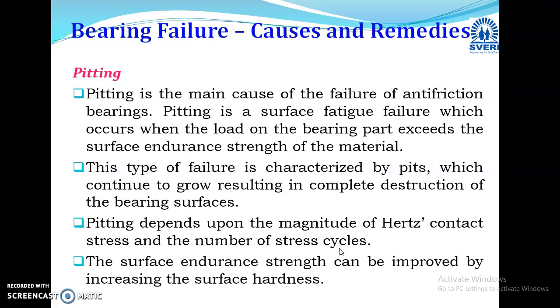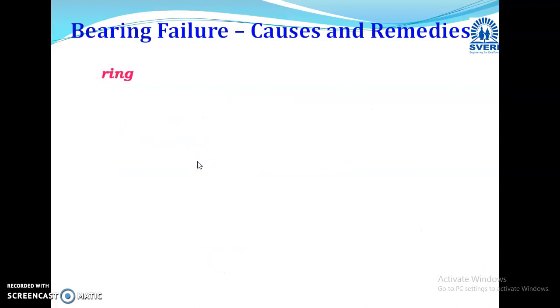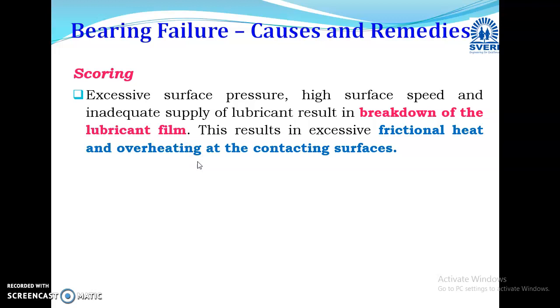And friends, for avoiding this, we have to improve the surface endurance strength, and it can be improved by surface hardness. So by selecting a good material having higher surface hardness, it will enhance the surface endurance strength and pitting can be avoided. Scoring.